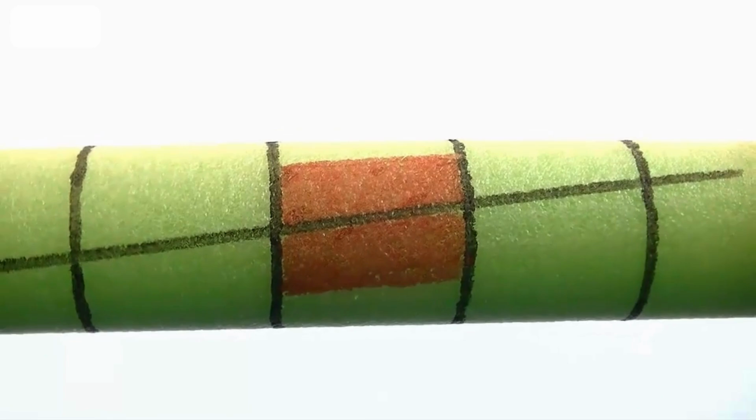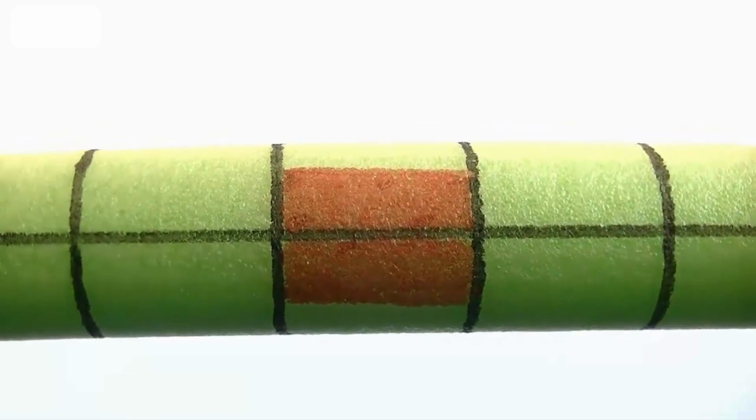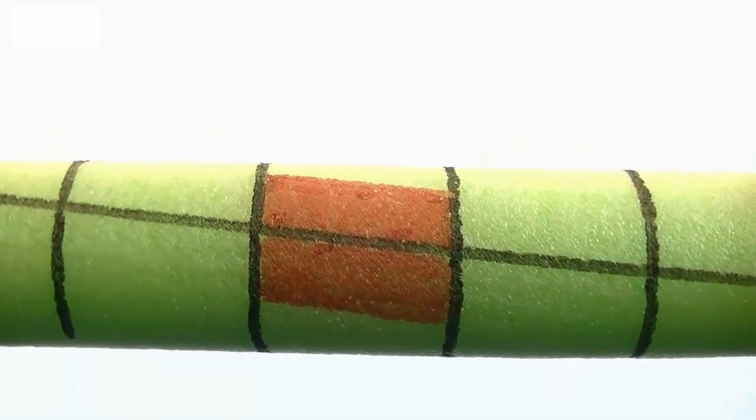By adding 2 more lines to the surface of the shaft, a rectangular element can be defined. Repeating the alternating torsional loading, the nature of this deformation becomes more apparent. As the lengths of the sides of the element do not change, it can be concluded that the element does not experience any normal strains. However, the element does rotate through an angle just as a square element subjected to pure shear would.